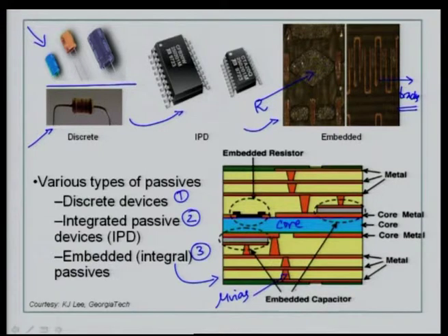And then you can see there is embedded resistor here, then there is an embedded capacitor that is generated as part of the system, then you can also have inductors generated, then you can have metallization done on top of these resistors and capacitors to connect to inner layer coppers by micro via technology. So, this is typically a high density interconnect scheme that you are already aware of from the previous modules, and we are now trying to see how we can devise a scheme for embedding resistors and capacitors in this format.